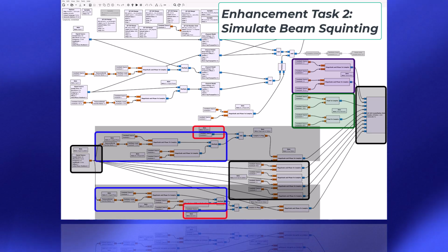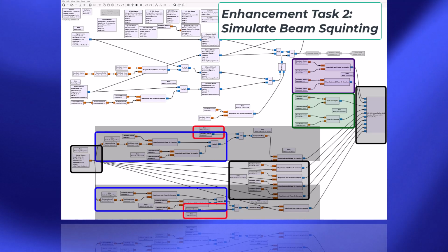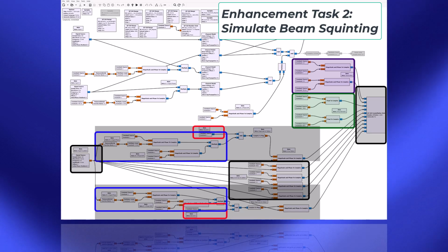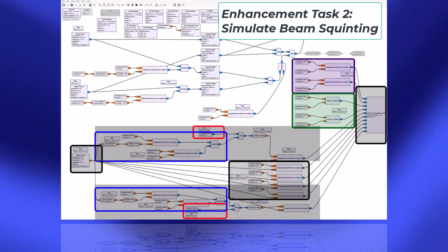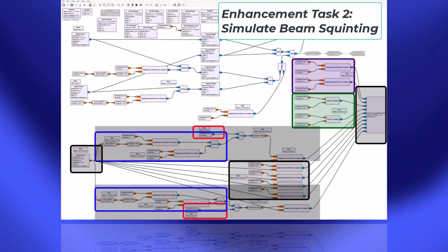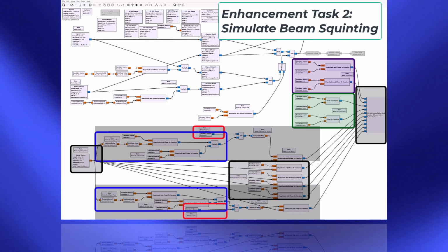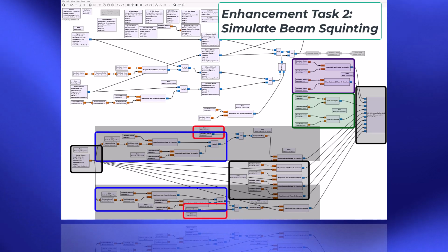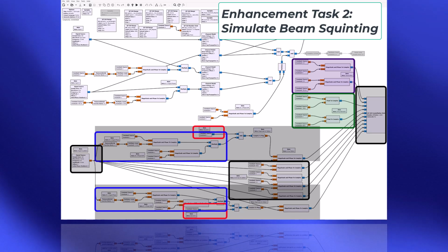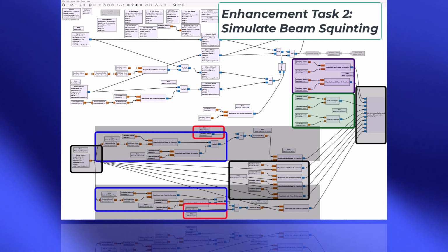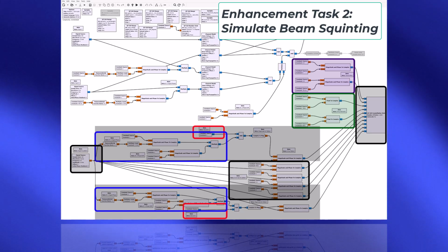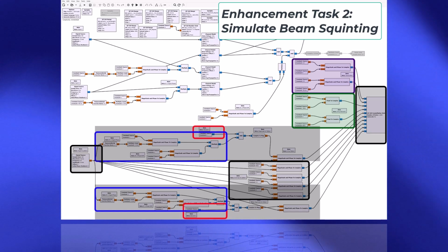So it'll be a higher frequency or a lower frequency, and in that case, you should use the wavelength that corresponds to the selected non-reference frequency in your calculation of the array pattern at that frequency. So you have an ideal pattern, that's the pattern based on your phase shift selected at the reference frequency. You have a non-ideal pattern that will be the pattern at the other frequency that you've selected, and those patterns in general will differ from one another. And you should be able to see the beam squinting effect that we talked about in the class.